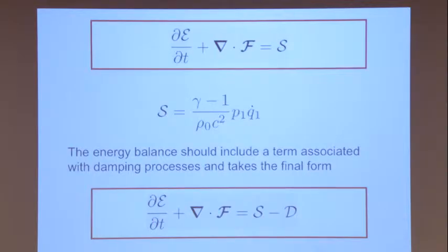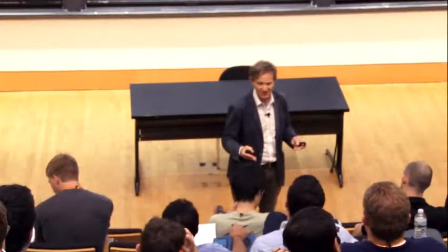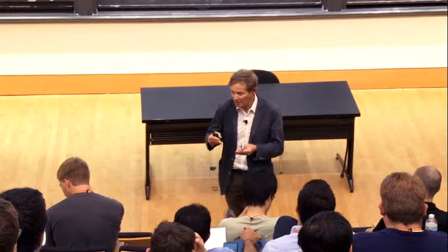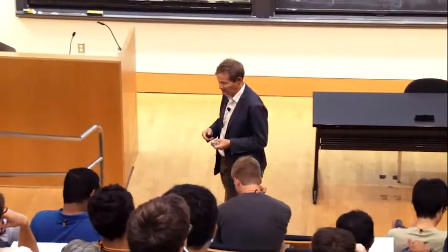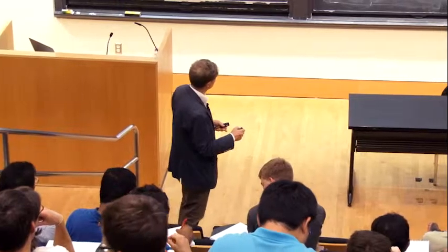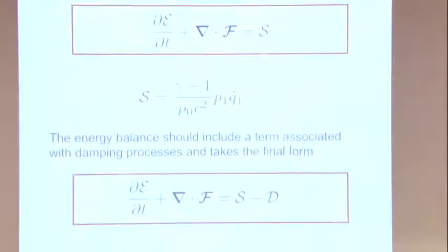But of course, we neglected up to now all the damping terms. But there is damping in systems, and more or less empirically, we put a damping term here. It's difficult, in fact, to predict damping. In mechanical systems, it's very difficult to get the right value for the damping. It's not easy, and often it's not so well known. Sometimes you can measure damping using resonance curves.